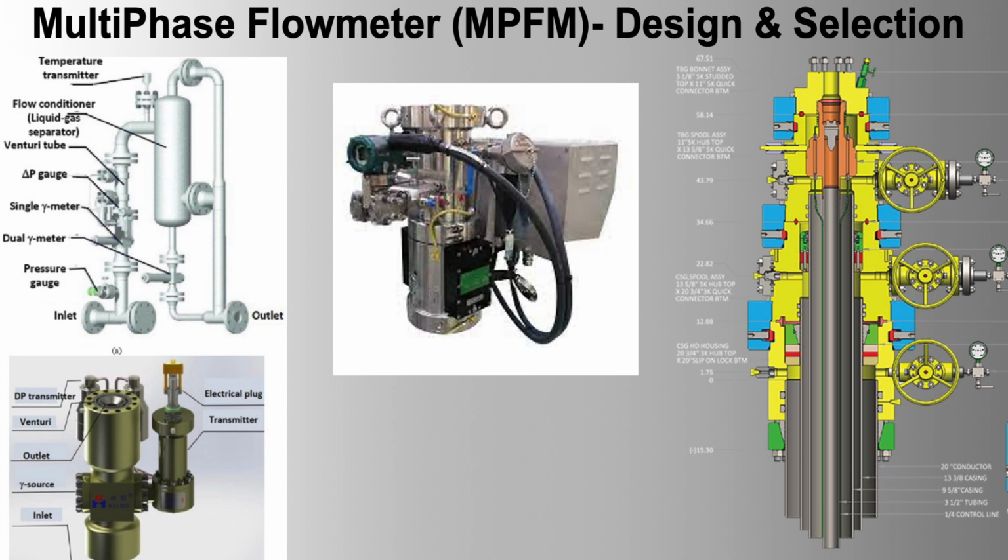4. High-pressure gas lift operations, flow meter type, Venturi-based multiphase flow meter with high-resolution sensors. Material, stainless steel with ceramic internal components for durability. Installation, installed in high-pressure sections with specialized anchors to withstand forces. Maintenance, modular design for easy replacement of worn components.